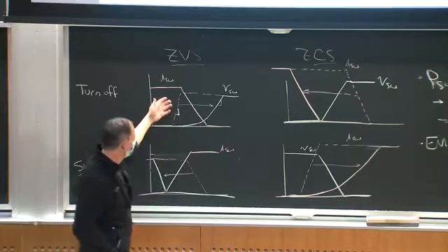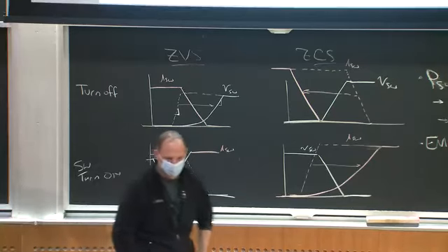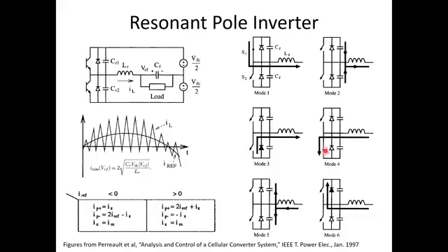So I have 0 voltage turn off, 0 voltage turn on. I will turn on the bottom switch, and what will eventually happen is, because the current's slowing down, the inductor current will reverse, and now I'll be building up negative current in the inductor, okay?